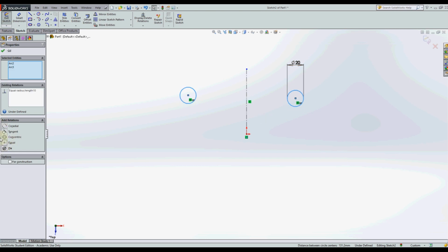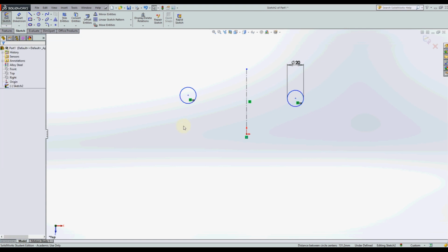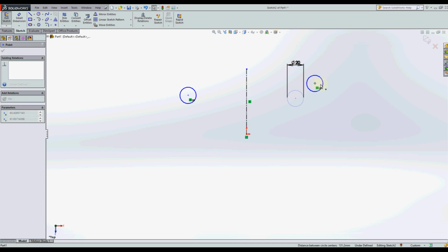You can see here, using circles you have multiple options. You can also say they should be different size, but the center of the two circles is equal. And you can also say, if you have two partial circles, that they need to lie on top of each other, which is the corradial option. So also using circles you have multiple options. I'm going to select OK again, so now the size is fixed, but the position is still totally independent.